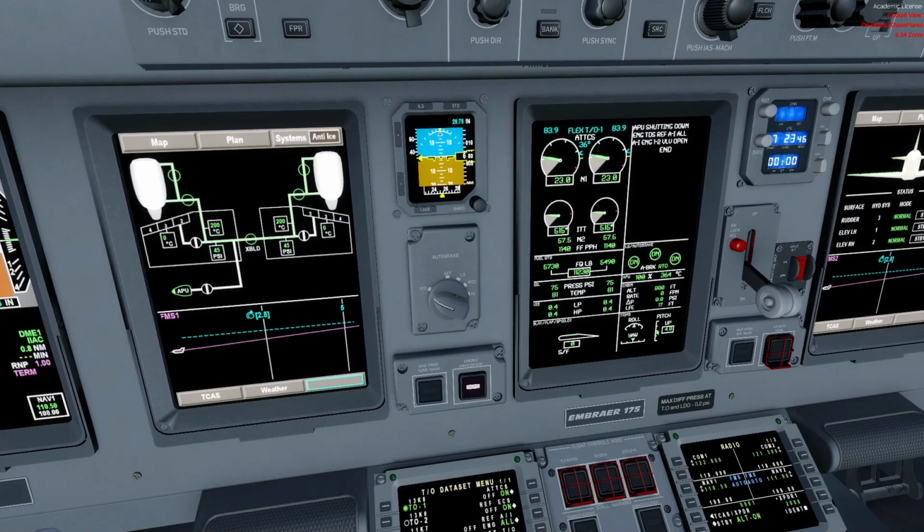So in this situation, with the APU out of the equation, this is what we would actually see at this stage. Engine anti-ice being green. Crossbleed, I don't think it would be open, to be honest, so that's probably not realistic. But then the wing anti-ice would activate at 40 knots, reaching either 2 minutes or 1,700 feet, which most likely is going to be the 1,700 because it's about a minute after takeoff.